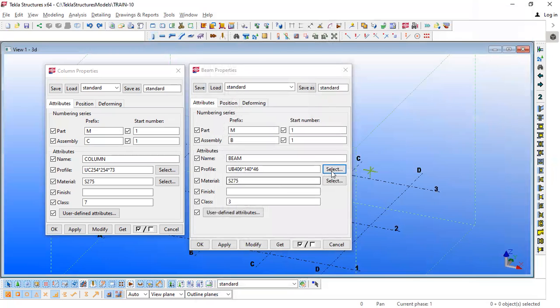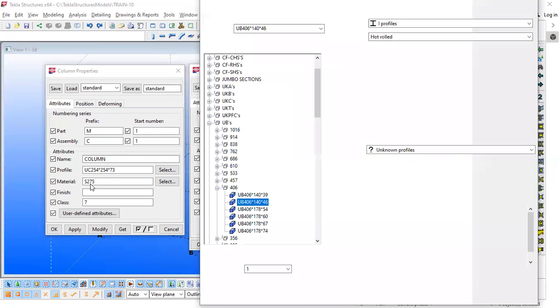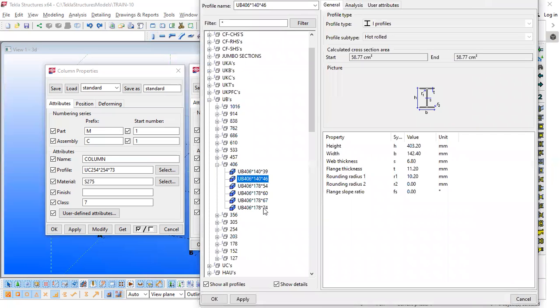For example, here you are seeing now UB, UC, universal beam, universal column. If I choose the Indian environment, then you might be seeing ISMB, ISMC, ISA, all those properties related to Indian standard. Or say if I have chosen the US environment, I'll get the wide flange members like W16, W10, W12, WT.